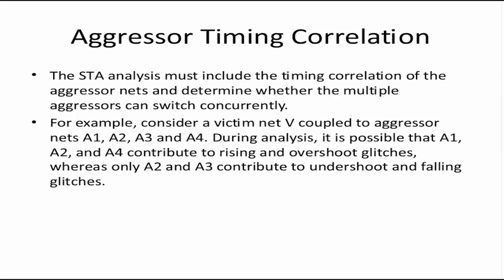So assuming the clock rises at 0, it knows about all the nets in that timing path which are switching with respect to this clock, and after what time they are switching. This is called a timing window, the arrival timing window. So PrimeTime, being a timing tool, knows at each node the arrival timing window, and it will use that arrival timing window analysis to determine the magnitude of noise.